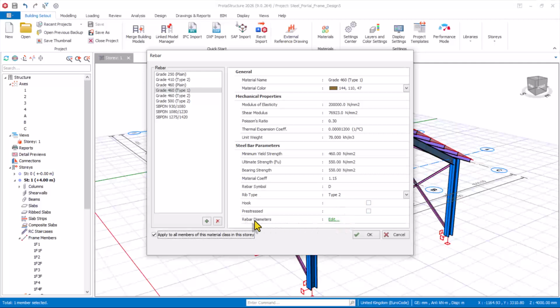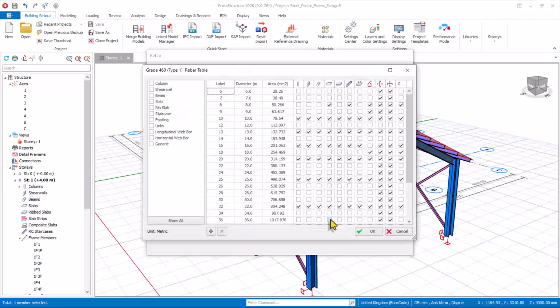For the rebar diameters, click on the edit provisions and then you have all of this. We go by minimum 16 mm diameter of reinforcement for the columns. The reinforced concrete column in this case is going to be the pedestal. We are yet to apply it.